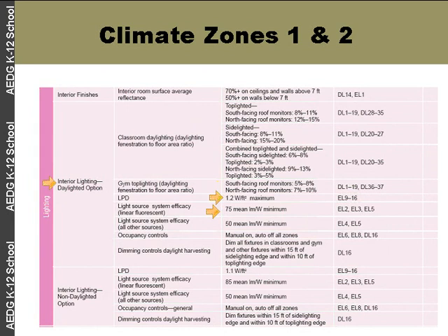And this is actually different, and we'll see here shortly, but this is a different mean lumens per watt than what we've seen so far. This one actually takes into account the ballast efficiency, where the first ones didn't. They were just the raw lumens per watt. Look in the catalog, here's the lumens, what are the watts of the lamp, divide the two.